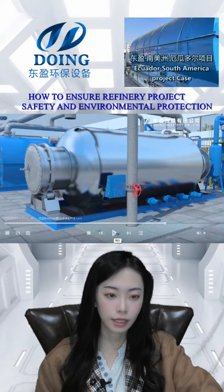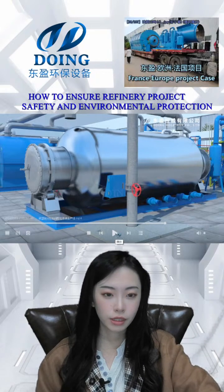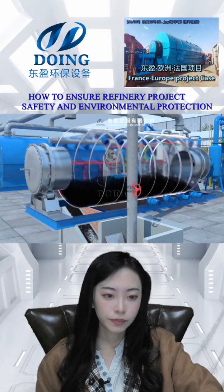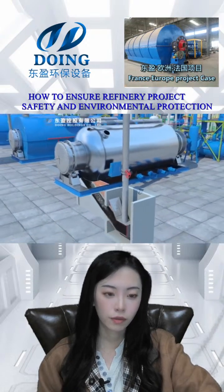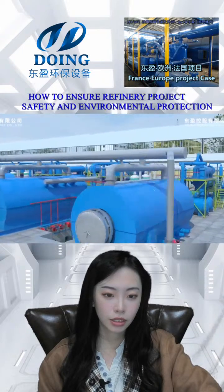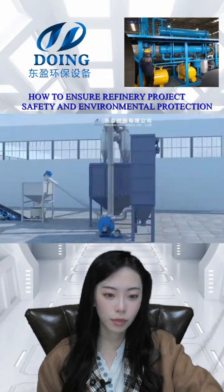We have 3 ways of slagging. This is one of them, the side slag, and we also have the front slag and back slag. Because this 3D video shows the side slag, let's share some of its advantages. First, it has 2 slag ports, so the reactor will discharge the carbon black twice in one revolution, which greatly improves the slag discharge efficiency. The second is you can see that the slag is discharged directly underground. It can prevent the carbon black from flying and polluting the workshop.